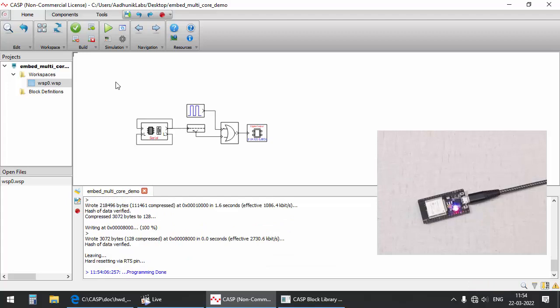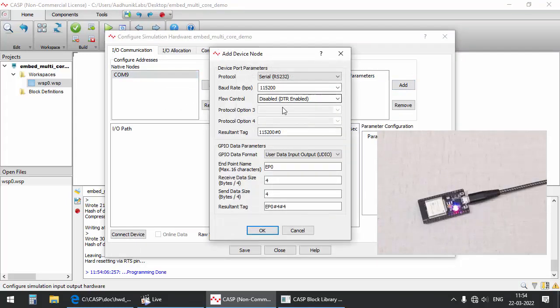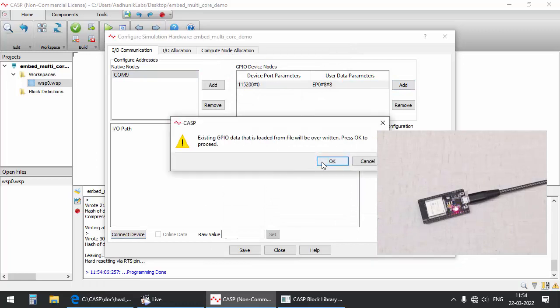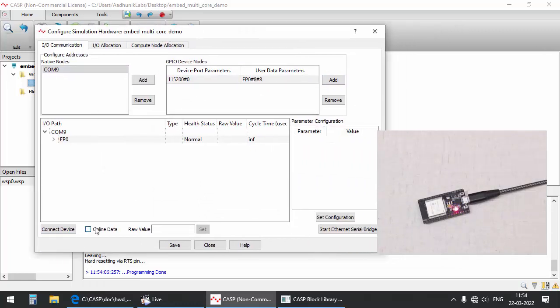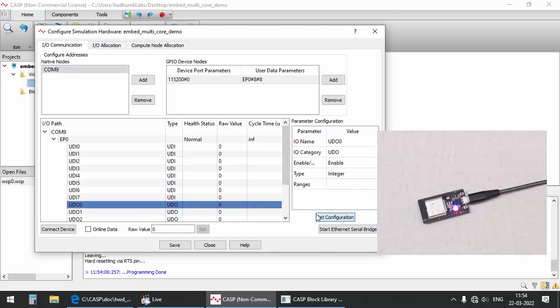Take a note of the rate at which the LED is blinking. We establish communication with the board from the host PC through the programmer serial port. After the communication has started, you may observe that the LED is blinking at reduced rate compared to earlier. This is because the same core has to run the code of LED blink logic and serial communication. You can also observe that the LED is controlled from the host PC.